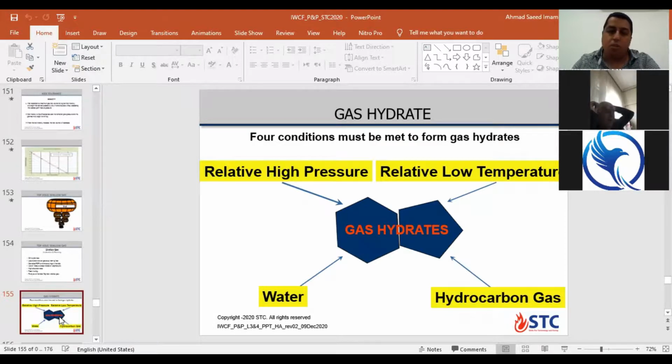If the gas hydrate forms in the choke line, you will not be able to break this gas hydrate like in a surface BOP stack, because this is something out of control below the sea level. In this case, you will use an inhibited mud system. You already add some inhibition chemical to the mud itself to try to prevent the gas hydrate.